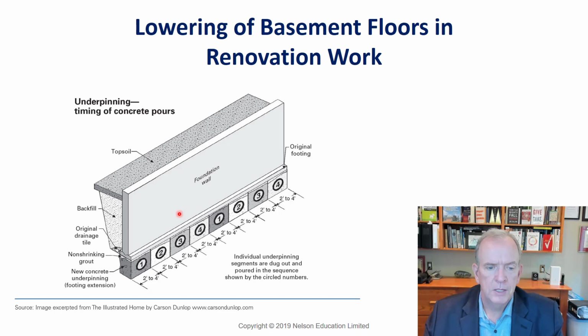The other thing that we can do, as I mentioned, is underpin an existing foundation if we need to lower it. I said that some older houses don't have a deep basement. Well, today, the value of a property could be drastically increased by increasing the square footage of the livable area. So a basement is a prime target, especially in an older house. If the basement is, say, 6'6", you could lower the foundation 2 feet. Now you've got an 8 foot or 8'6" ceiling height, and you usually have ducts and different things in the basement, but it'll still make it a nice livable area compared to the older basements with not very much headroom.